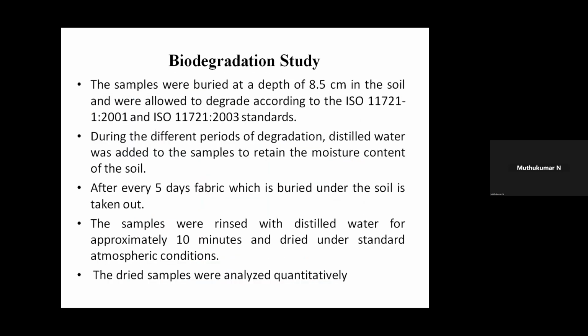Finally, we carried out a biodegradation study. The biodegradation studies were carried out as per ISO 11721 2003 standards. For this study, we kept the samples in the soil at an 8.5 centimeter depth. During the different periods of degradation, distilled water was added to retain the moisture content of the sample. After every 5 days, the fabric buried under the soil was taken out. The samples were rinsed with distilled water for approximately 10 minutes and dried under standard atmospheric conditions, and the dried samples were analyzed quantitatively.